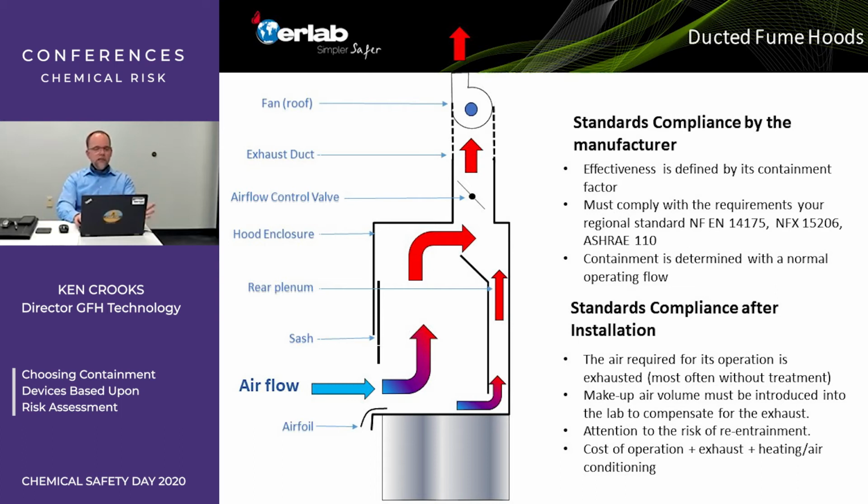Ducted fume hoods, in case you don't know, sometimes people are amazed by this, almost all the time, just fully exhaust that contaminant to the outside. There is no treatment, there's no filtration up on the roof. There are times when there certainly is, but the vast majority of ducted fume hoods are just exhausting to the outside. And so how that looks from a building perspective, and again, another side view of the fume hood here,